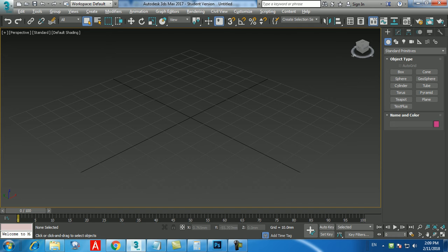So for bend, let's use it. If you increase the iterations more, it freezes and will crash. This is the turbo smooth iteration. Even the task manager will never respond.